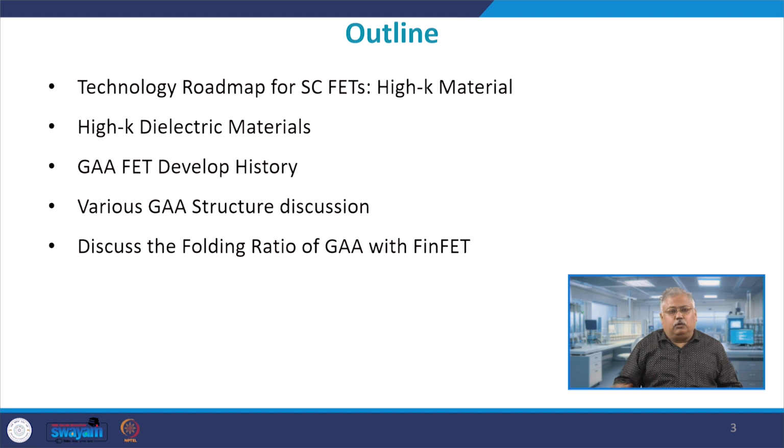So, the first outline for this lecture will be to give you an idea about the roadmap for short channel FETs, and that is basically using a high K material. What is the meaning of high K dielectric material? A brief history so that you can appreciate how GAA FET were formed, various gate all around structures, and then finding the folding ratio of GAA with respect to FinFET.